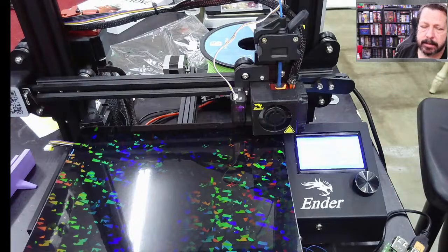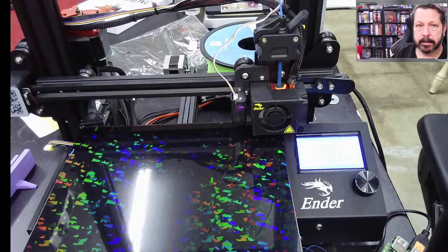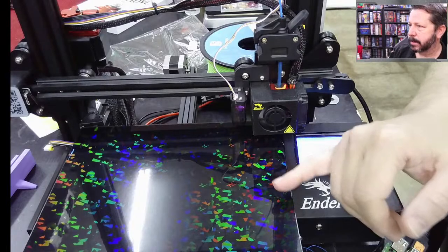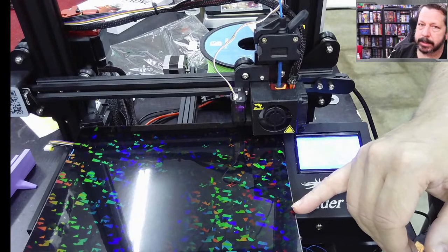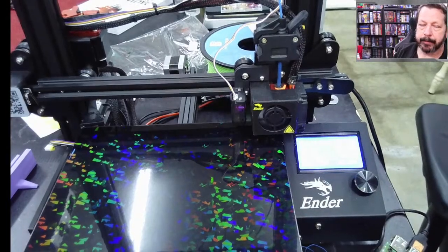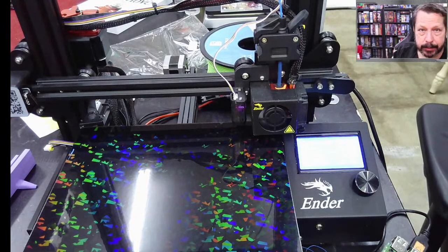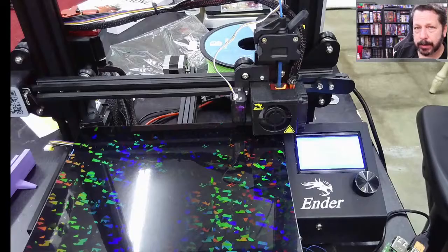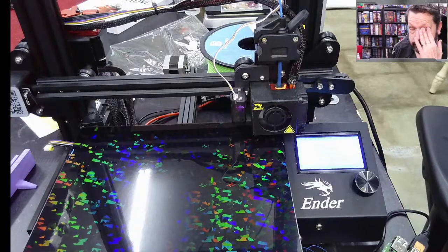I think, if I'm thinking right, the smooth PEI and smooth glass are not good for PETG. I think it'll stick too well to the smooth surfaces. Now this one, it's not. This was smooth, but it's not going to stick to it too badly. The textured surfaces, so the glass with the dots on it, or the textured PEI sheets, those are fine. But if you're doing smooth glass or the smooth PEI, you might want to put something down like either tape or glue stick.